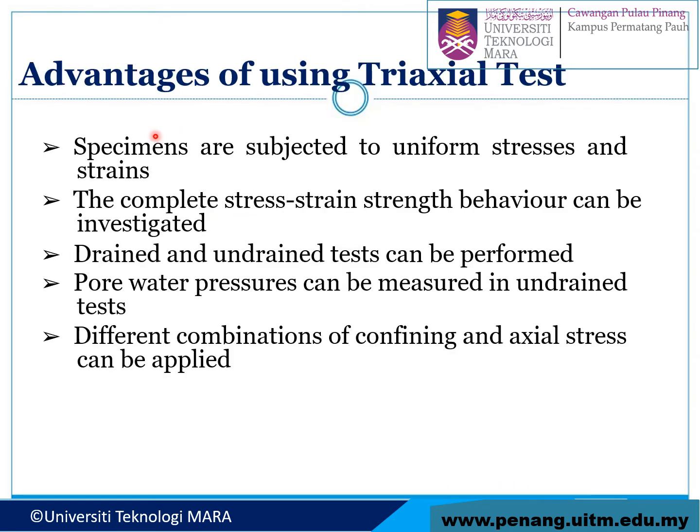What are the advantages of using the triaxial test? First, specimens are subjected to uniform stresses and strains. The complete strength behavior can be investigated. Drained and undrained tests can be performed, if you compare to the shear test, so it's different. Pore water pressure can be measured in the undrained test. Different combinations of confining and axial stress can be applied.